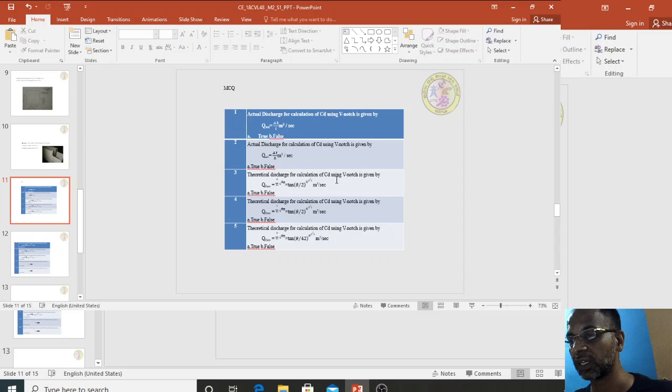Theoretical discharge for calculation of Cd is given by 5 by 13 root 2g tan theta by 2 h to the power of 5 by 2. This is wrong, that is B. Theoretical discharge for calculation of Cd using V-notch is given by 7 by 15 root 2g tan theta by 2 h to the power of 1 by 2. This is also wrong, B. Theoretical discharge is 8 by 15 root 2g tan theta by 2 h to the power of 5 by 2 divided by...